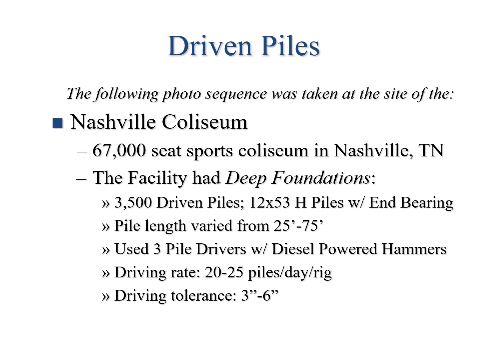This facility had deep foundations. 3,500 different driven piles. 12 by 53 H piles with an end bearing, and each pile length varied between 25 and 75 feet. The reason for that is hitting the rock down below, it pretty much goes until they know the drill point to where they've hit rock, and it varies in the depth for each hole driven.